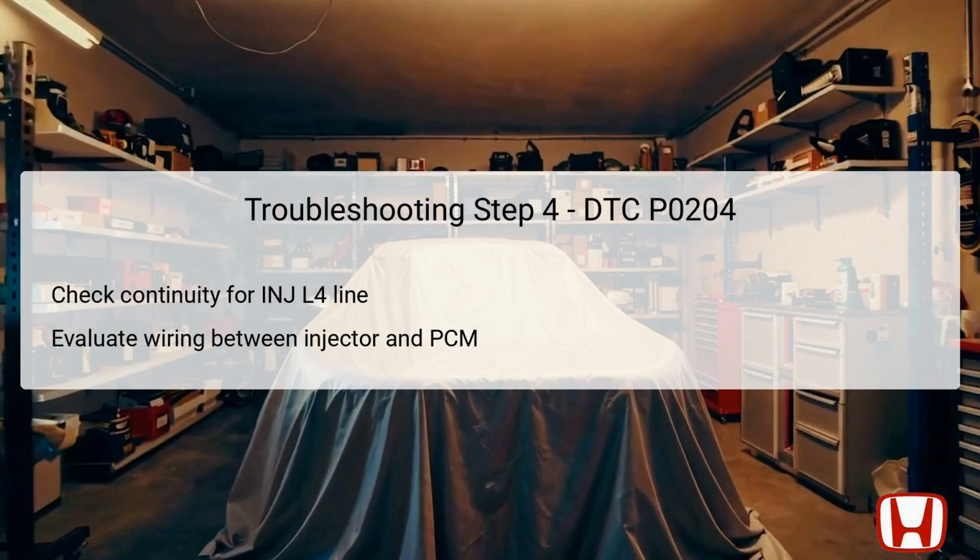To do this, keep the vehicle in the off lock position and ensure that both the number 4 injector and the PCM are disconnected.